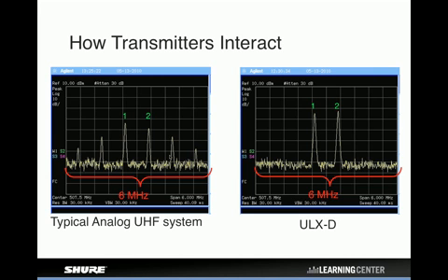Just like in the antenna webinar last month, where we said don't keep adding more gain to your antenna system because it can cause more problems, same thing here in RF. More power is not necessarily the solution. Now, if you're just using one wireless mic and you're trying to get 1,000 feet of range on a golf course, have at it. Crank it up. The FCC allows licensed users up to 250 milliwatts if your hardware can get there. But for multi-system applications, lower is generally better.